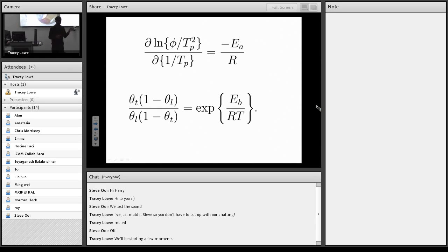If I put a square specimen in TDA, I will get a different result from a cylindrical specimen. And the chemical reaction analogy simply isn't accurate because we get diffusion from inside to the outside. A more elaborate theory deals with local equilibrium. That means that you have a trap and you have the lattice in which you have diffusible hydrogen, and they will be at equilibrium. So this is the fraction of hydrogen trapped at traps, and this is the hydrogen inside the lattice, and this is again the binding energy of hydrogen to the trap.